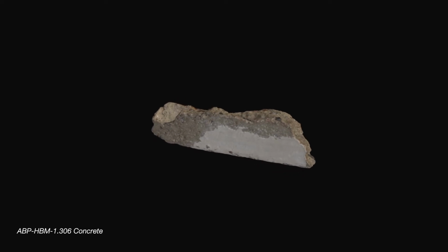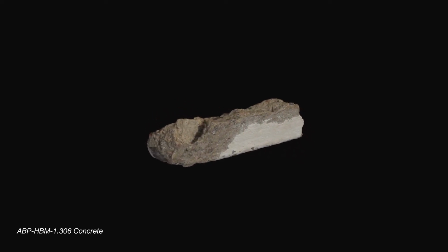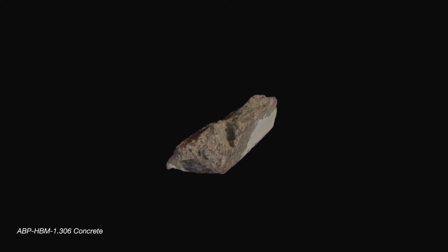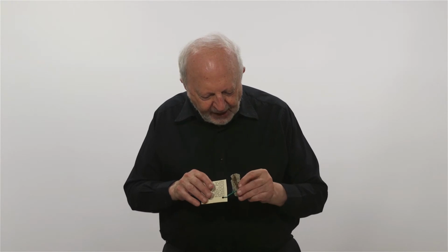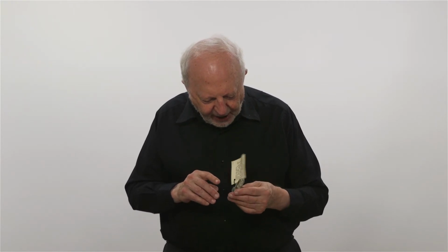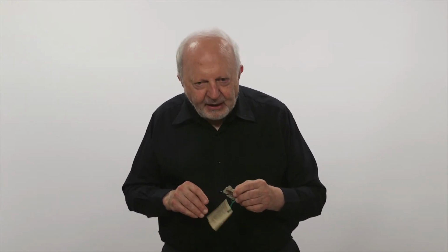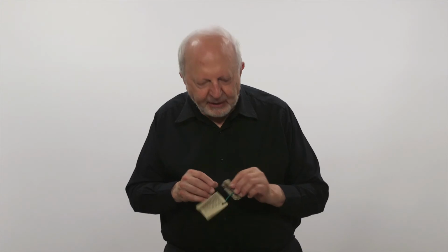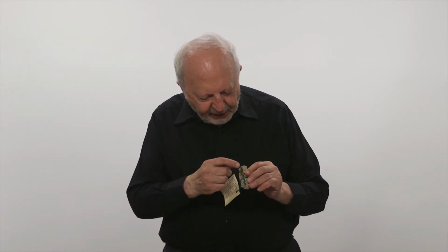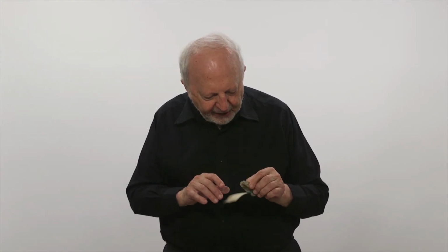But its problem was that the reinforcement didn't have enough cover. You have to have enough thickness of concrete over the reinforcement to stop water penetrating and the reinforcement rusting. And also, in this case, the quality of the concrete was questionable. And there were sea breezes coming in, so salt came in. So you can see here the reinforcement is not bonded properly with the concrete. Ideally, you get a firm fix between the concrete and the iron.